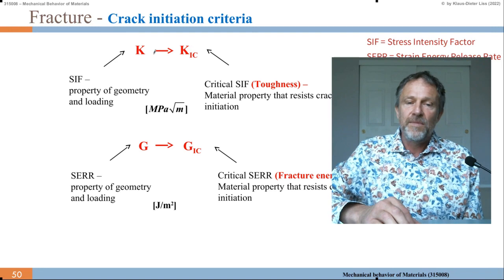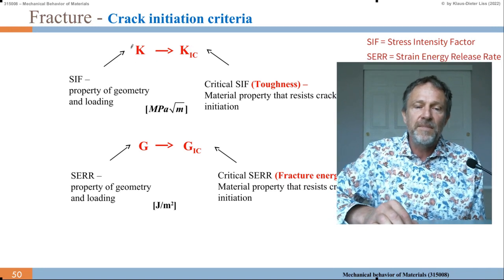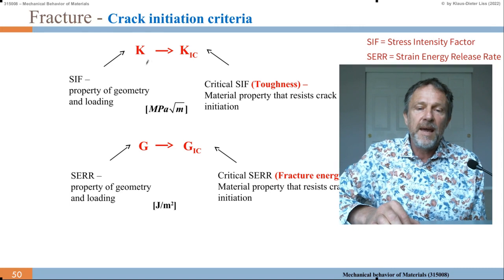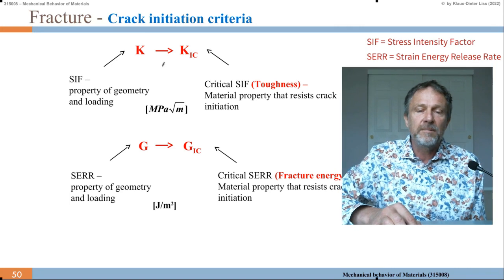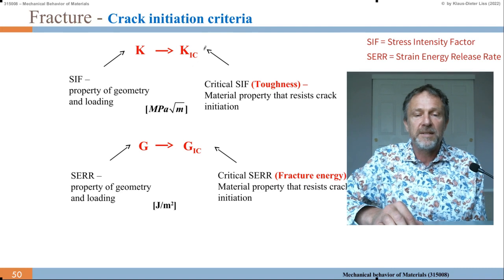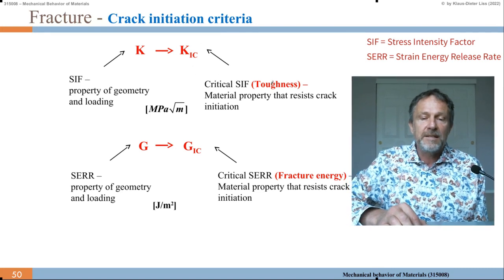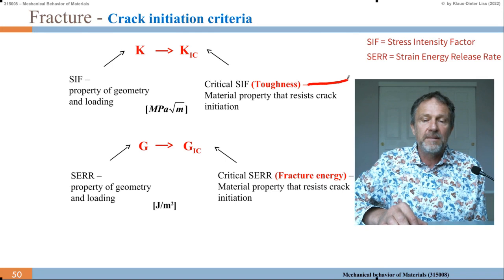So now we have a crack initiation criterion. We have the stress intensity factor K, which has to surpass a critical value, K1C. And this we call the toughness.